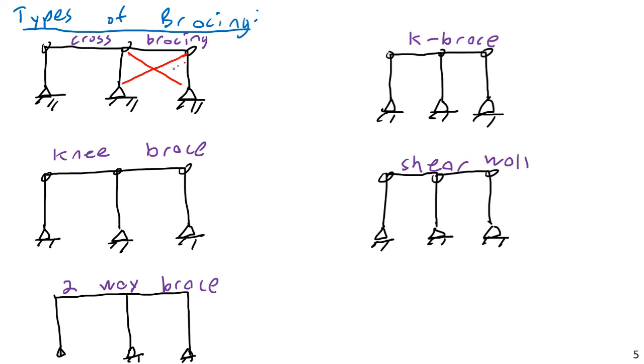And you have a set of them, so in other words, if you have a load in one direction, one of them can go into tension. If load is coming from the other direction, then the other one can go into tension, and neither of them ever has to carry compressive loading. And so you can get away with long, slender members, and if you remember from mechanics of materials, long, slender members are terrible for compression because they have a tendency to buckle, but they're very efficient for tension. They have no problem with tension.